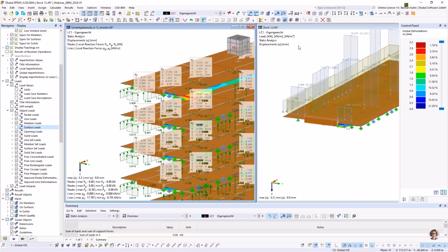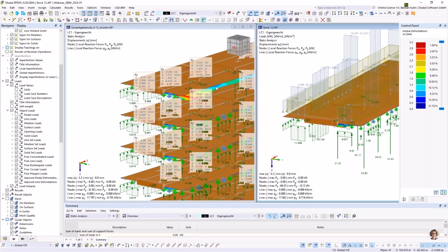And of course, you also have it on the story 12, 5.8, but as this is not regarding the load transfer from the top, this is already the error that you are making here in this 2D model, because you are not taking the force from the story 13 to the story 12. This you have to do in this separate position.